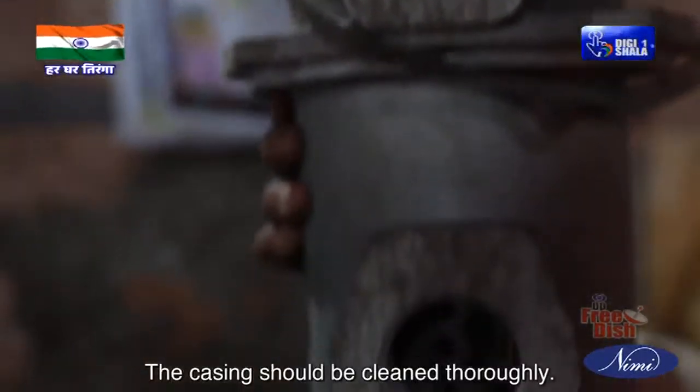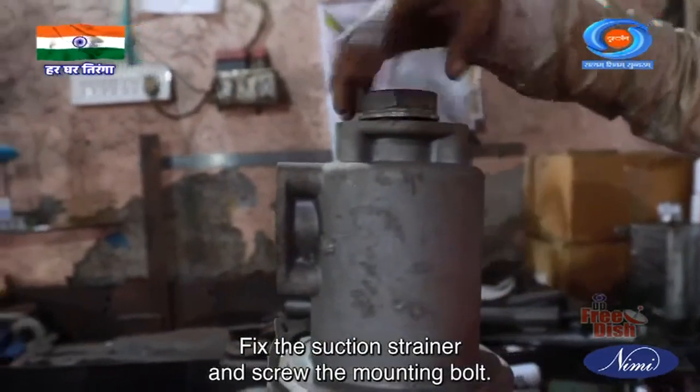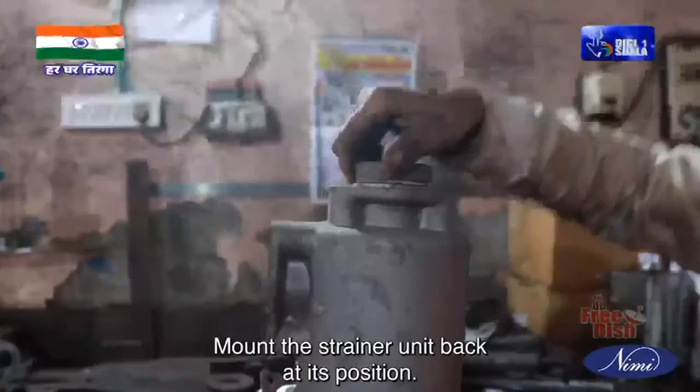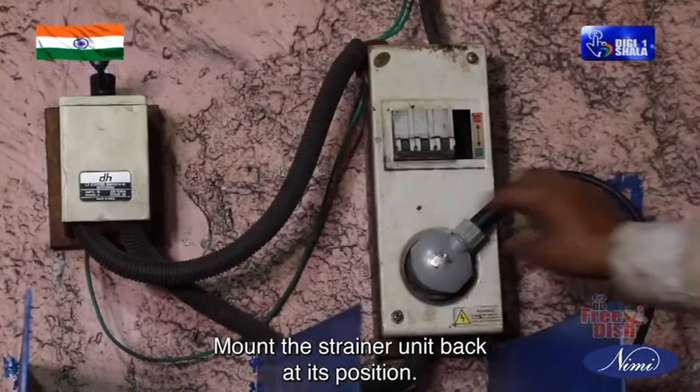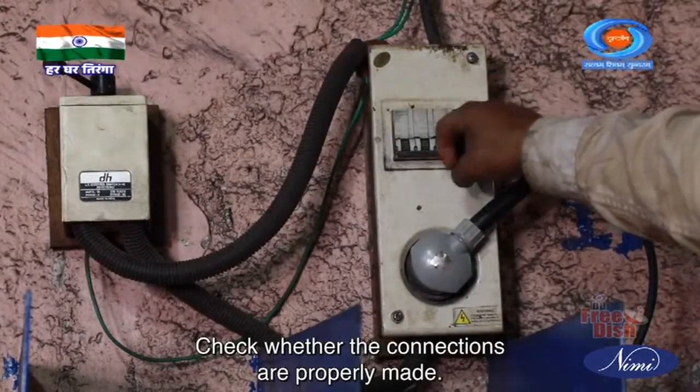The casing should be cleaned thoroughly. Fix the suction strainer and screw the mounting bolt. Mount the strainer unit back at its position. Check whether the connections are properly made.